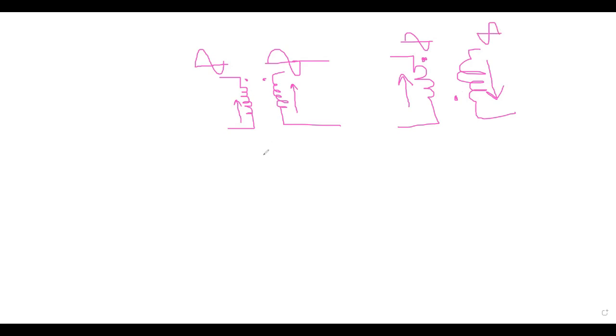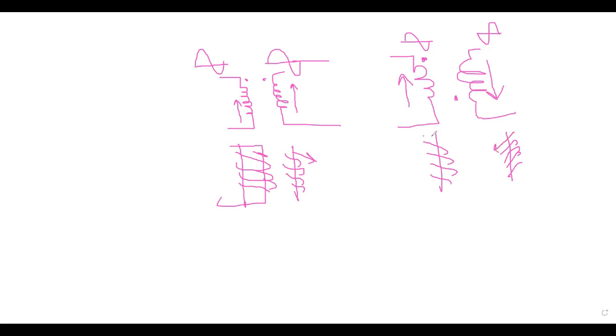I mean that winding, or how they are connected. So you know how these are connected. The coil is connected in this way. For both, the coils are connected in this way. The current is flowing this way. And if you see this, the coils are connected in this way, but here the coils are connected in this way. The flow of current is opposed: subtractive polarity.